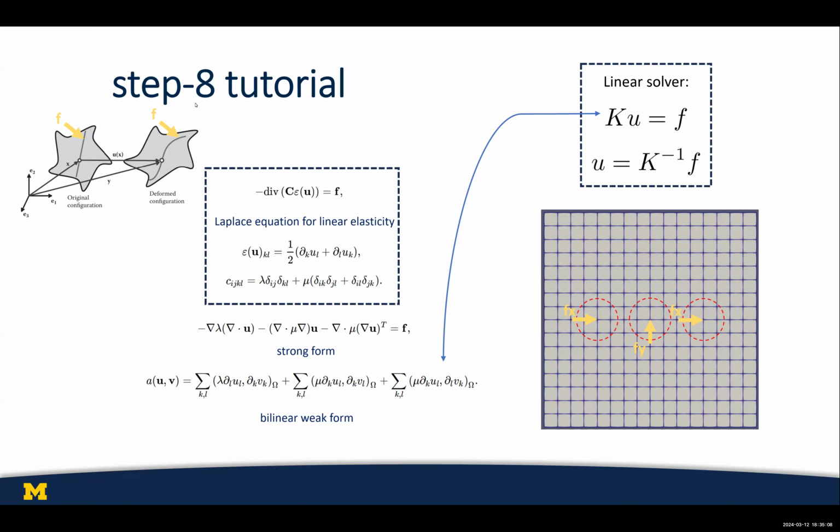Linear elasticity. That's where we're starting. So there's some calculus, and if anyone wants to talk about finite elements after, I can go into details, but there's some calculus that you essentially calculate a huge matrix of your stiffnesses at this point, how stiff is it in both directions. And if we were in a linear situation, we can just invert that matrix and solve for our displacements. Exactly. So now let's have some fun.